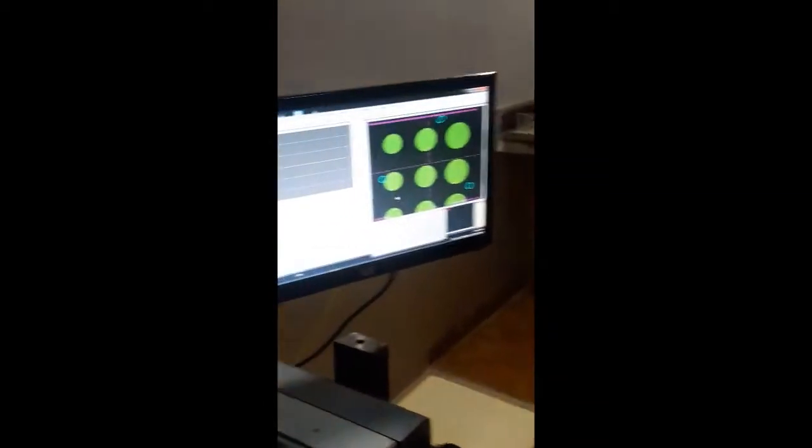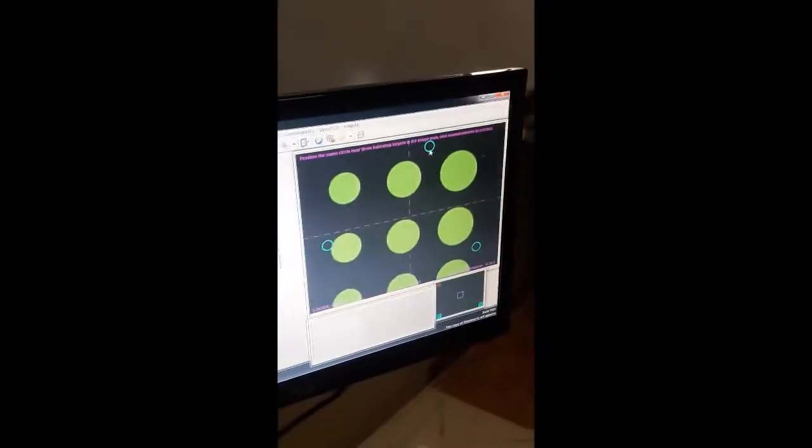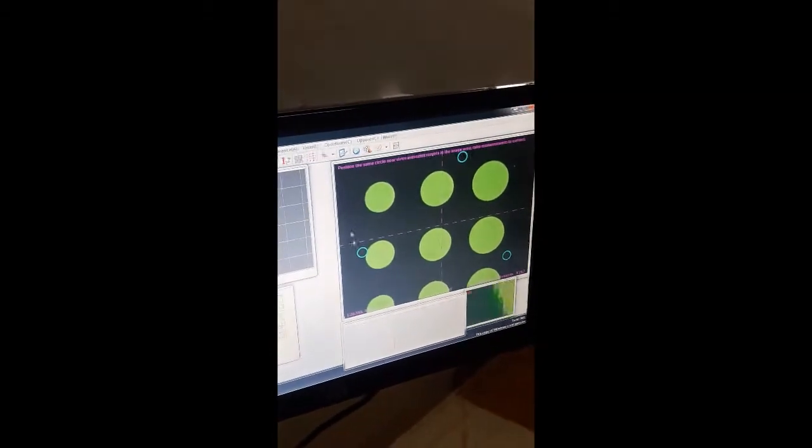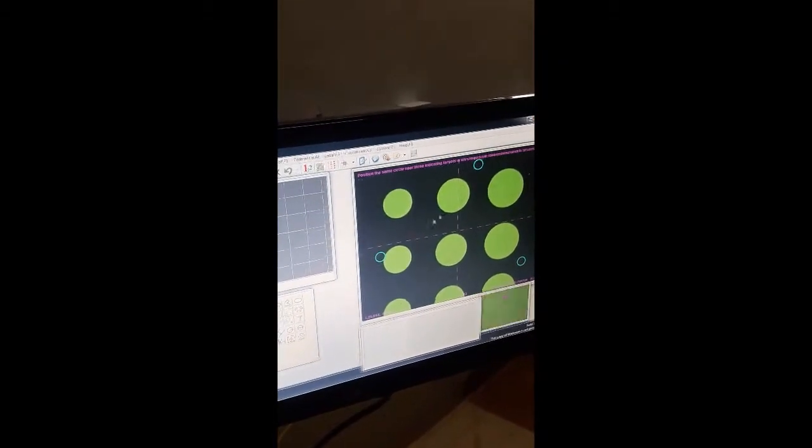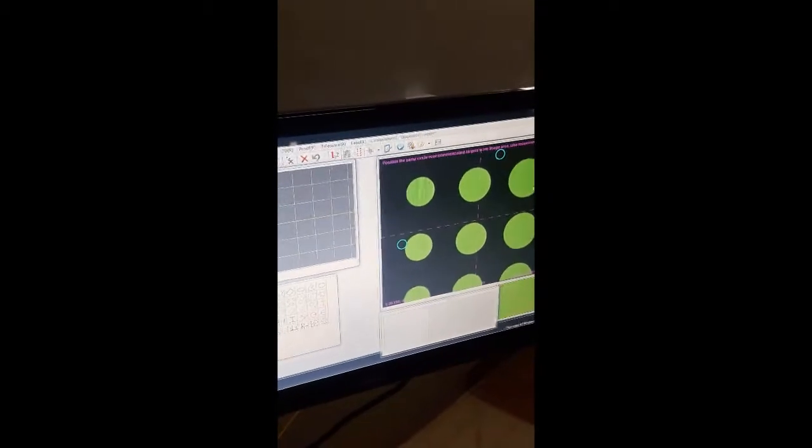Before starting to measure, you have to do the calibration using the calibration specimen. The calibration specimen is made up of transparent and opaque regions so that whatever light you want, you can use it. It has some standard circles in it. So you have to go to the proof and image correction, 3 circles. When you click it, you will get 3 small circles. Now choose any one of the available circles here and bring that circle there to mark. So let us choose the top